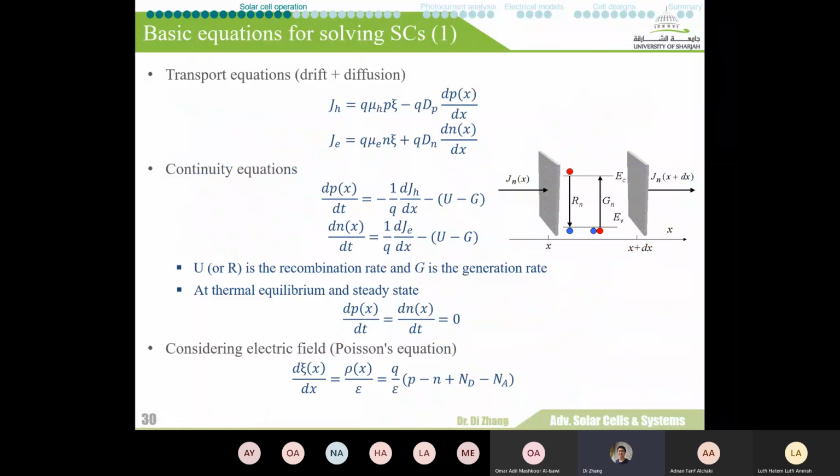So let's summarize what we have so far, and also introduce the new parameters, so that we can see the difference between a p-n junction in the dark and a p-n junction operating under illumination. First of all, we can combine the drift and diffusion equations we saw before. For solving the p-n junction before, we didn't use these two equations. But now, if we introduce illumination, we expect additional drift and diffusion current, and that's why we have to use them for solving the equations here.